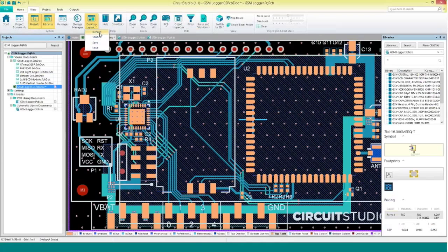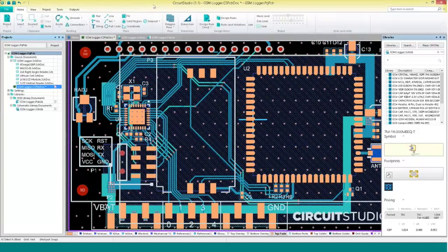There's lots of great shortcuts here in CircuitStudio. In your ribbon menu, you can hit the Alt key on the keyboard, and it'll display the different shortcuts for the different ribbons. The home is the H, so I'll just hit that. And then it's just going to show me all of the available shortcuts for every menu item. Let's see, routing's a good one. I'm going to hit H to open that up. And then interactive routing, H again.